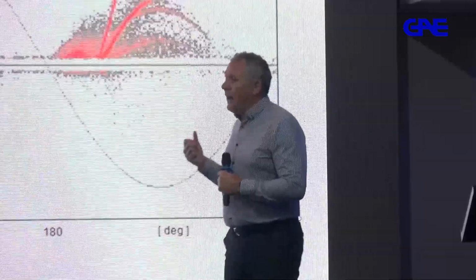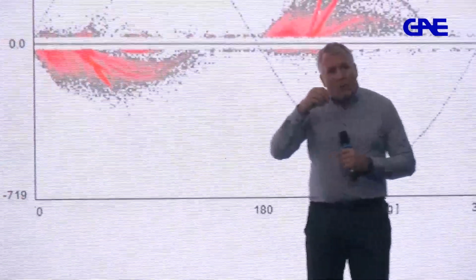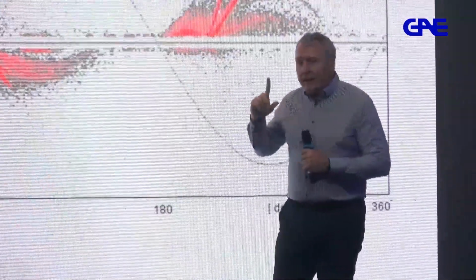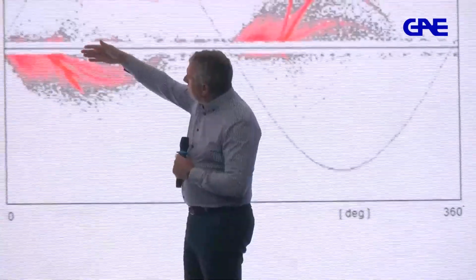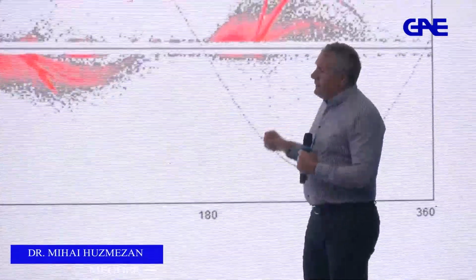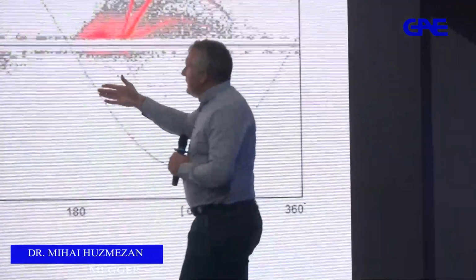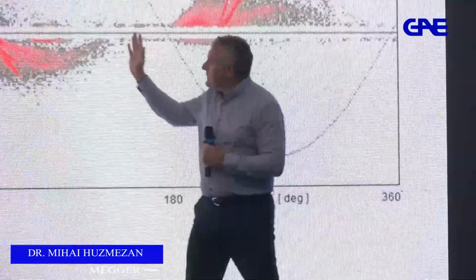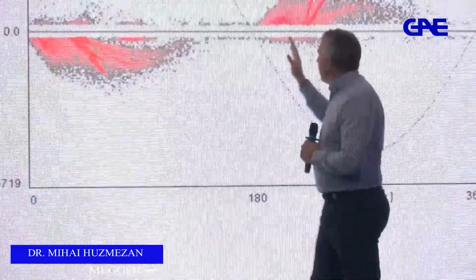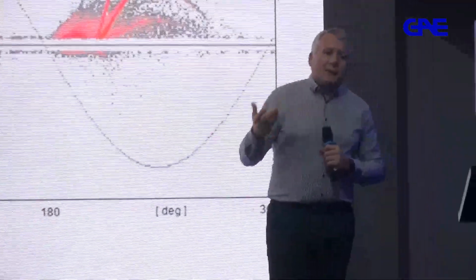So now, in the case of a rotating machine, in the case of a generator, what's happening is that there are small voids inside of this wound mica tape. And those voids will give this kind of pattern that you see here. These are voids. Then also at the end of the stator you have discharges. So you can see discharges: things that happen on the positive side of the cycle have a certain meaning, and things that happen on the negative side of the cycle have another meaning.